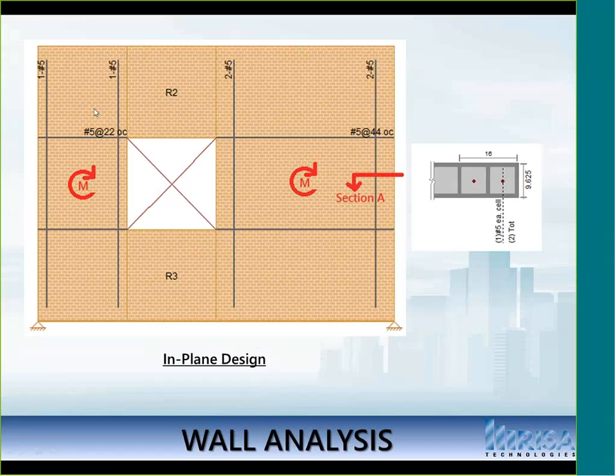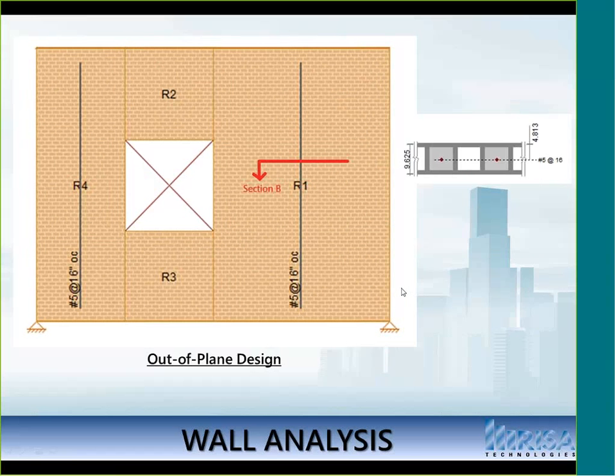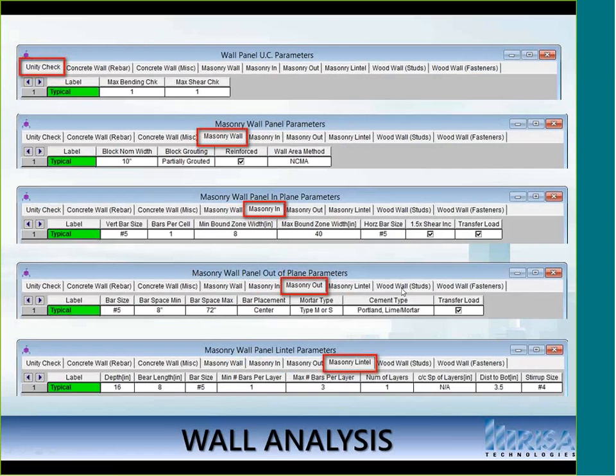And what will happen is the in-plane forces will transfer as an axial force through this region and this region, such that these 2 regions will carry all of the in-plane forces in the wall, as opposed to sharing some with these, and that relates to the sort of overturning style bending.